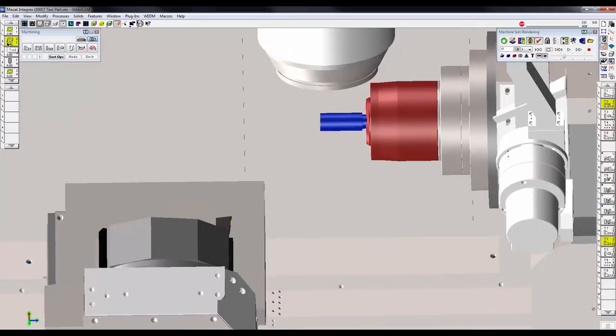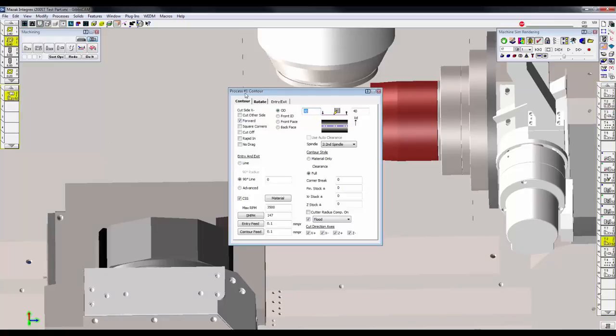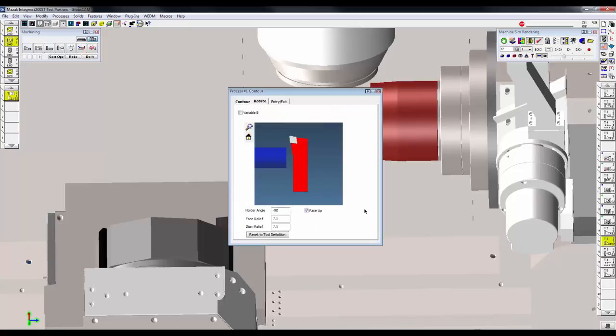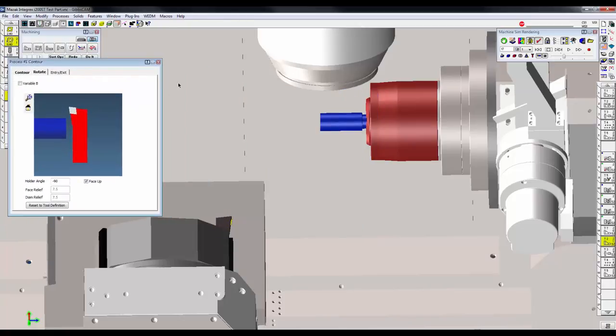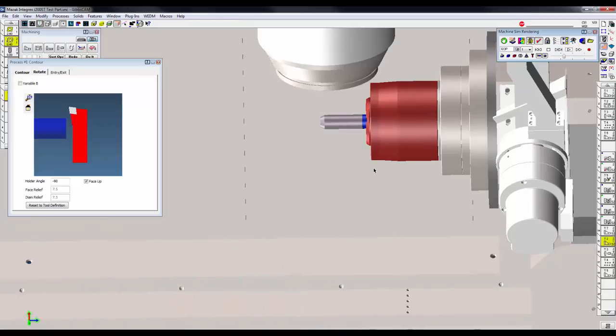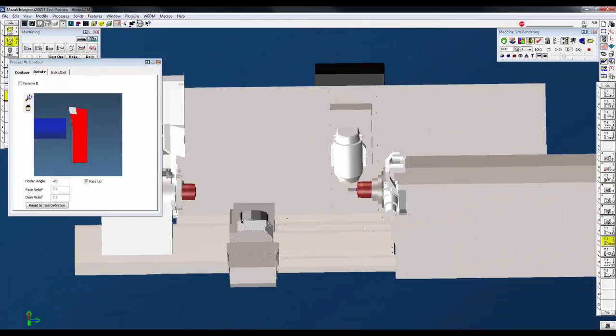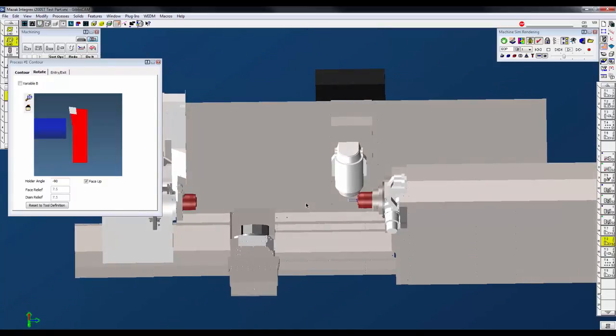It's the exact same tool in the exact same position, except on this tool path, we actually have it rotated at -90 degrees. So when I play this, you can see that it's going to just come up and do that cut. So you don't have to create another tool or rotate or do some trickery in there. These are just a few things that Orientation Turning is going to help you with if you have any of these situations on your machines.